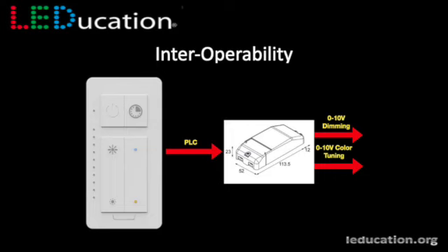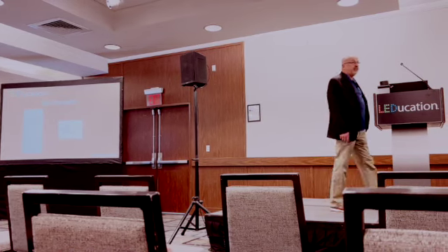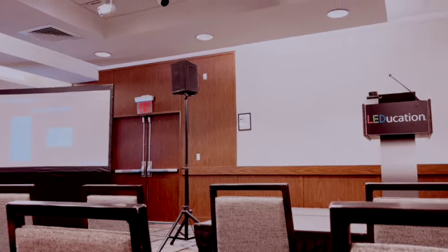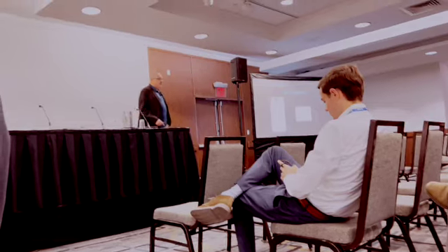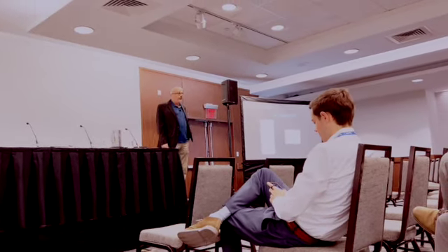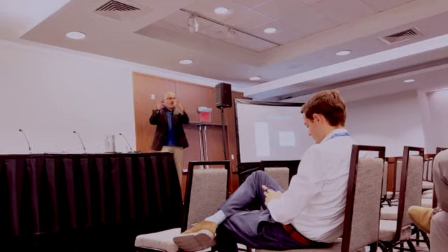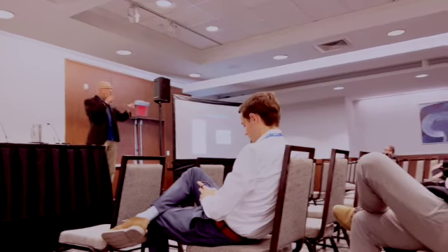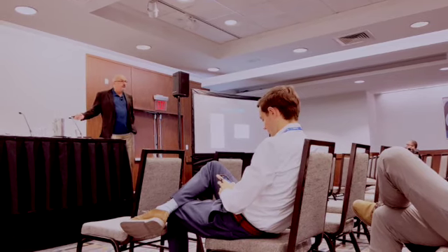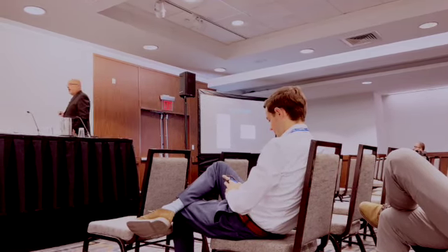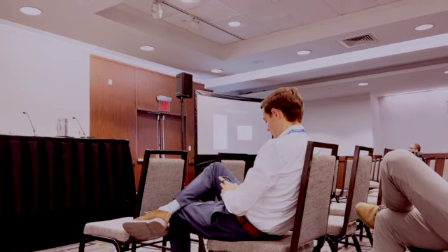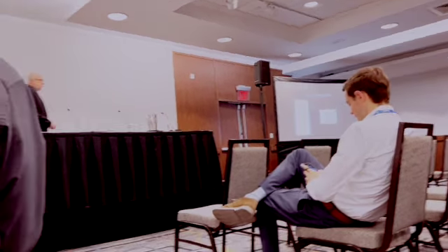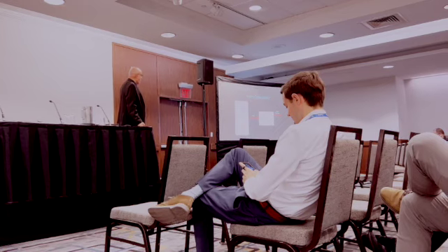Right? So out from our wall switch, through the supply wires to that little module, and now our fixture understands everything we're trying to tell them. We want you to be half dim, we want you to be full bright, we want you to be off, we want you to be quarter dim. It'll do it. We can also do color change with this, just by having 2 0 to 10 volt signals come out of that module, going to the 2 sets of different color LEDs inside the fixture. And we mix those using the controller, and we can do circadian rhythm. We can do color change, we can do room adjustments, anything like that. There it is.